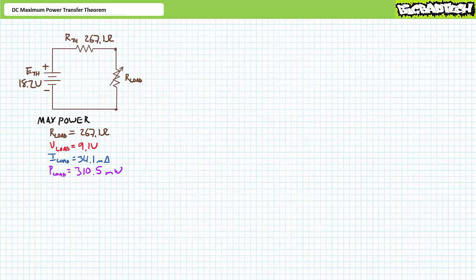The maximum power transfer theorem really is that simple. A variable load resistor will receive maximum power from a circuit when its resistance is exactly equal to the Thevenin's equivalent resistance for that circuit. The only tricky parts are 1. Obtaining the correct Thevenin's equivalent circuit, and 2. Using it correctly. Note the load resistor is but one of two resistors in the equivalent circuit, the other being RTH. Again, at maximum power conditions, our load drops half the Thevenin's equivalent voltage.